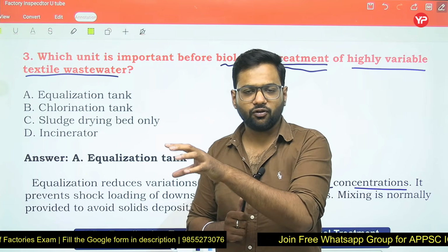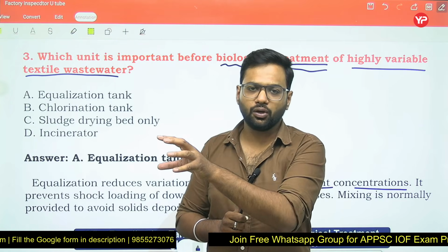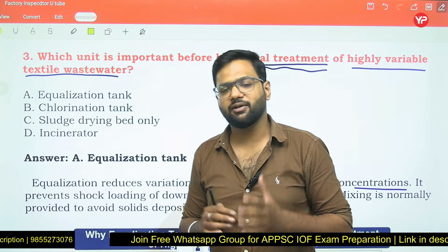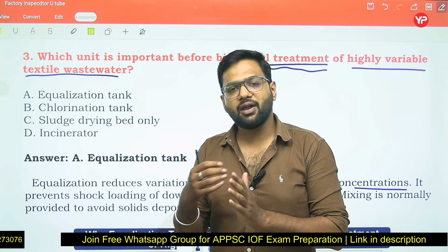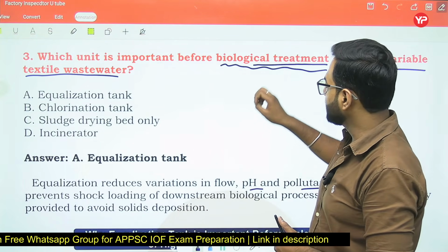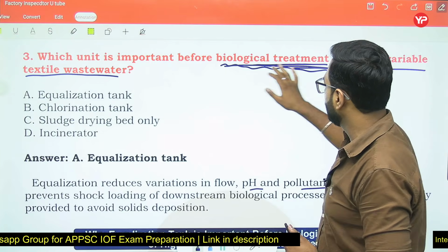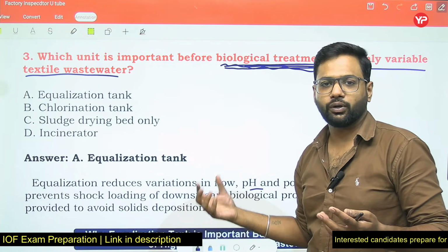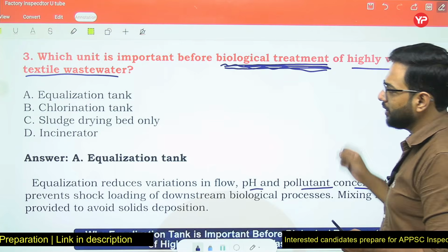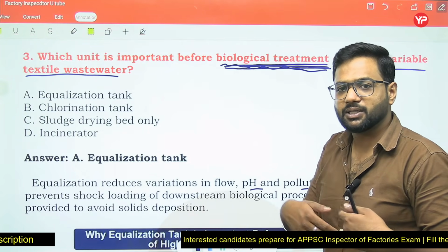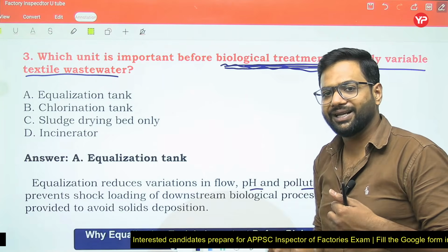So these methane formers play a very crucial role in the decomposition, and they work in the narrow pH range of 6.5 to 7.5. That's why we have to maintain this pH during the digestion process, and we want to avoid fluctuations. We don't want any type of fluctuations in the primary sedimentation tank. If fluctuation is there, pH can rise or decrease.